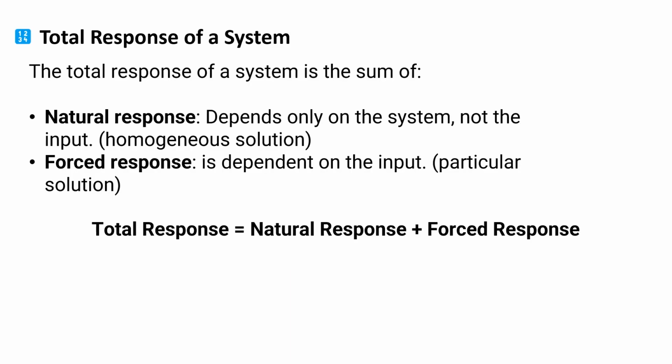So in general, the total response of a system is the sum of two parts. It's the sum of the natural response and the forced response. The natural response depends only on the system and not on the input. So if you remember back when you were taking differential equations, or maybe you're taking it now, when you solve a non-homogeneous differential equation, you have a homogeneous solution and a particular solution.